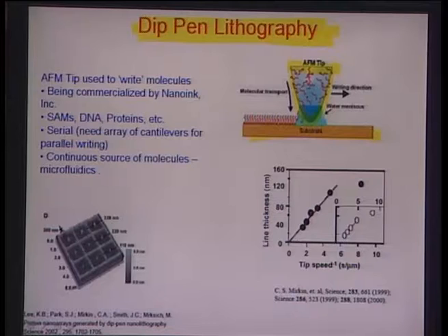What we do is create some favorable temperature and humidity conditions, so that there is this monolayer of water, and we choose the surfaces in a manner that there is a tendency for this water meniscus to adhere more to the AFM tip than the substrate, and so you can drag it along with the tip as the tip moves around.